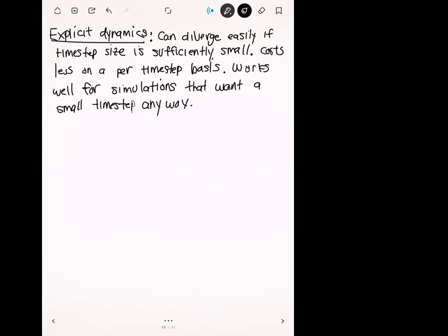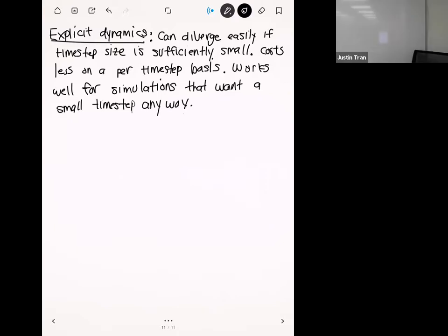So right now, you can see you have motion, so you have gravity, you have pressure, but you need to fix the structure. Without any constraints, the structure is unstable. You just need at least one. You can do both ends, it really depends on the situation. Usually when you get this warning, it's under constrained. So you do that.